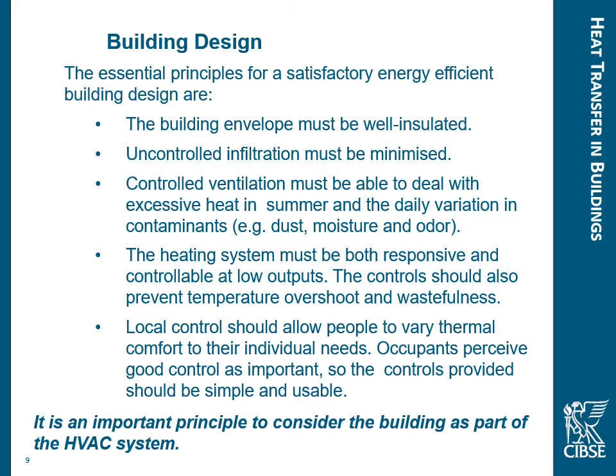So it's an important principle to consider the building as part of the HVAC system because the building requires the HVAC system to heat it or cool it, and if the building is poorly insulated and it's got leaky windows and leaky doors, our building services, our HVAC system, will need to work twice as hard to keep up with that heat loss.